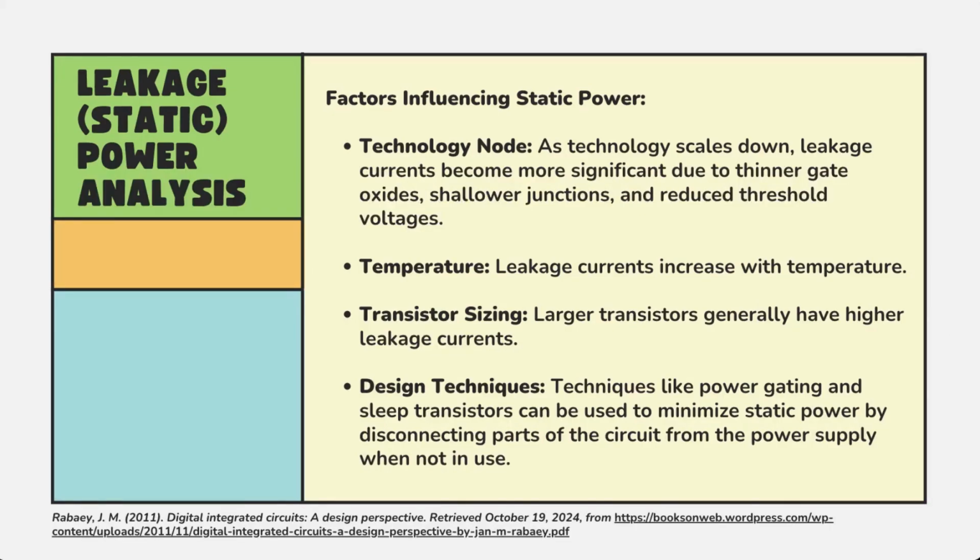Leakage static power analysis. Factors influencing static power. The first one is technology node. As technology scales down, leakage currents become more significant due to thinner gate oxide, shallower junctions, and reduced threshold voltage. Temperature. Leakage current increases with temperature.